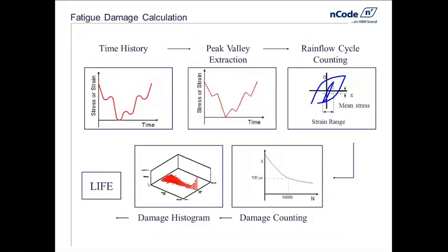Looking graphically at what it's doing, what I have here is a forward fatigue calculation where we have a fixed time history going through rainflow counting. Each cycle is compared to the fatigue curve to get damage. Individual damages are summed up to give a final life.